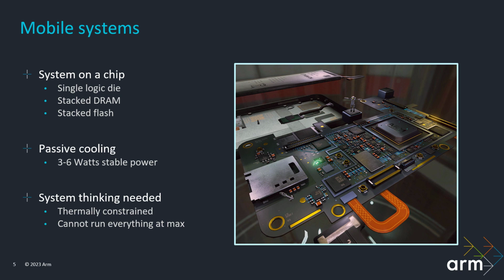This does enable a different way of thinking about optimizations compared to, say, a traditional platform like a games console. For a console with a heatsink and a fan, they are designed to run all of the components at max performance all the time. So you can generally break it down into 3 independent optimization problems looking at CPU, GPU, and memory bandwidth. Because we're sharing a thermal budget, you really have to make the whole package work well together. And even if you're GPU bound, you may find that optimizing your software workload or your memory bandwidth actually helps because it frees up thermal budget that can be assigned to increase the GPU frequency.